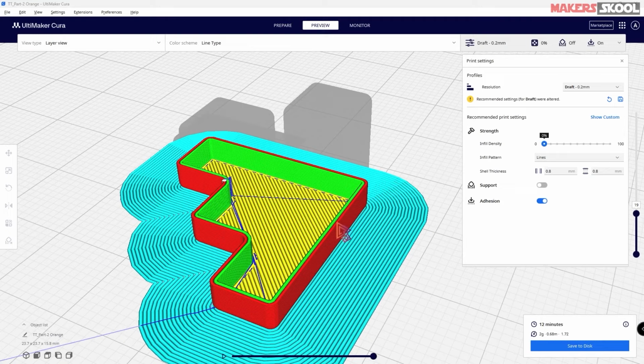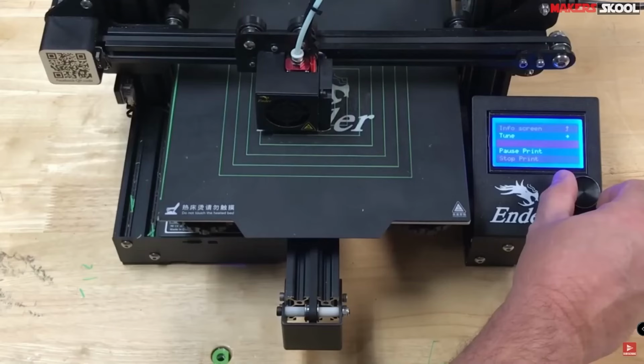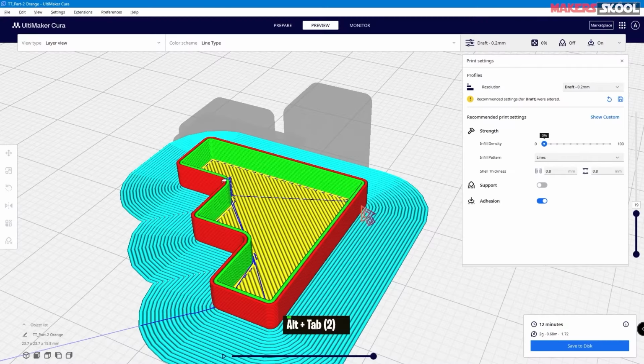As we have discussed earlier, in a standard 3D printer, the nozzle diameter is 0.4. So when the 3D printer starts printing a single line, the width of the single line is the 0.4 nozzle diameter. If it has a 0.6 nozzle diameter, then the line width will be 0.6. So the width of a single wall with a 0.4 nozzle diameter will be 0.4. So if there are two walls, the width will be 0.8. As you can see, the shell thickness width is 0.8.